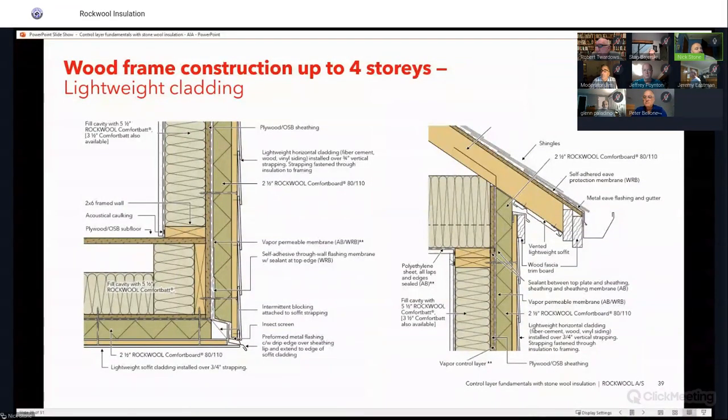Get some kind of material, some kind of WRB that's wrapping over this plate. You can staple it down or whatever it may be, and that's going to really help make that continuity connection much easier for them when they get to the stage of detailing all that stuff.